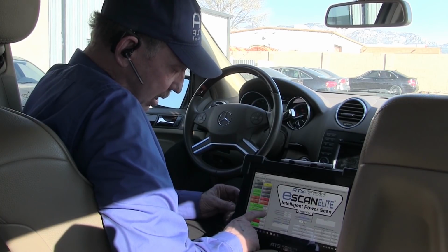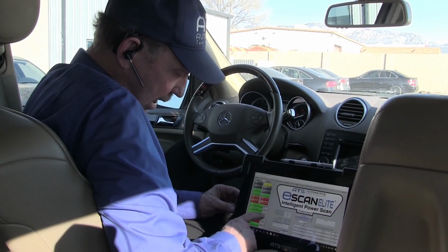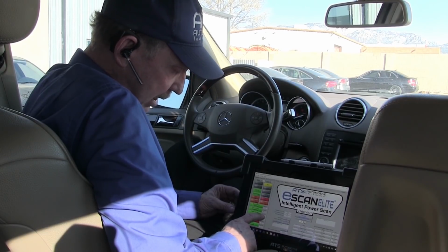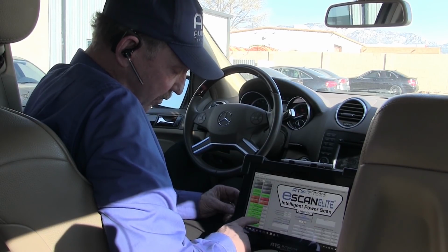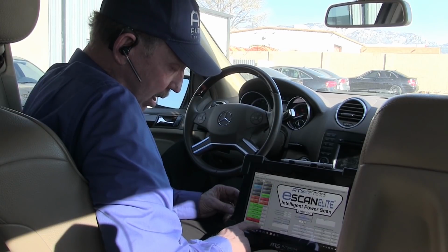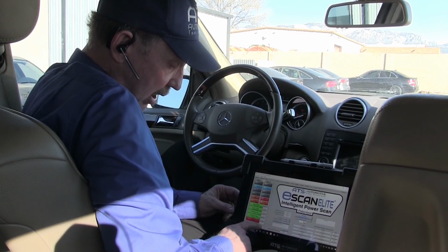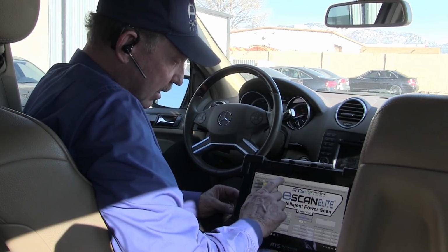Time to temperature, I'm at 188 degrees. The engine vacuum is 15 inches, and that's okay. I'm a mile high. I'm in Albuquerque. So 15, 16 inches of vacuum is what I expect a motor to make. Charging voltage is good, 14. DTCs, we have 6 DTCs set and the monitors have been run, so the shop did not clear the codes. If they did, they drove it enough to run all the monitors again.